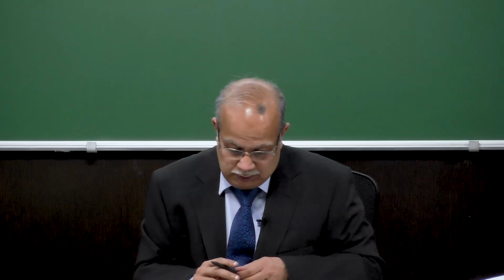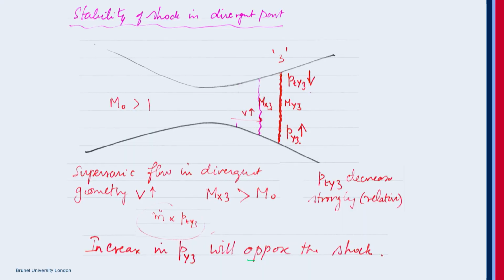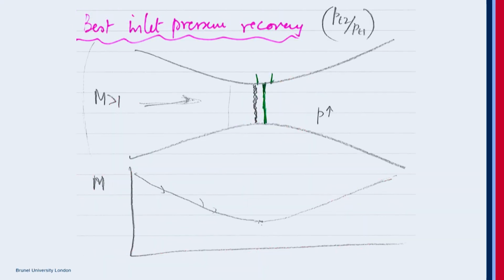So an increase in the static pressure will oppose the shock. This is what you see here. When you have an unstarted inlet, we really want to make sure this shock you see here is placed exactly at the throat.